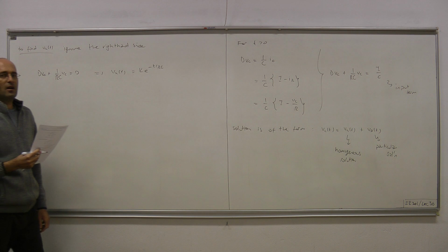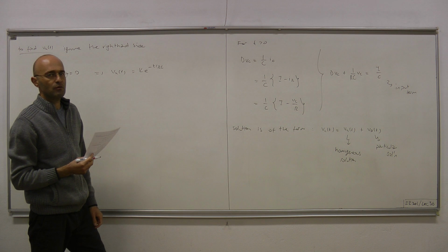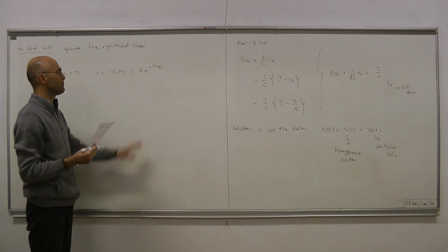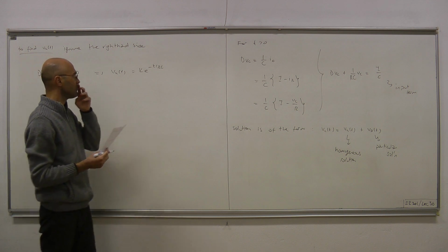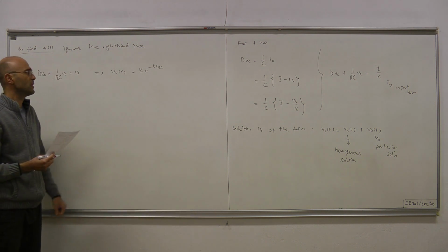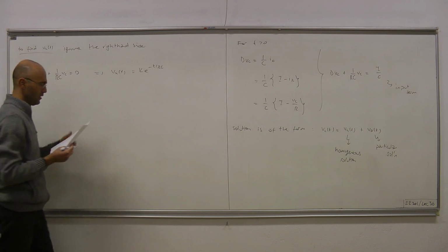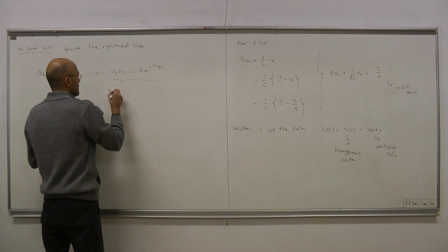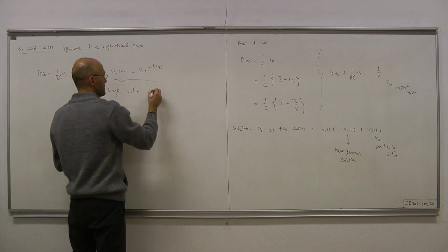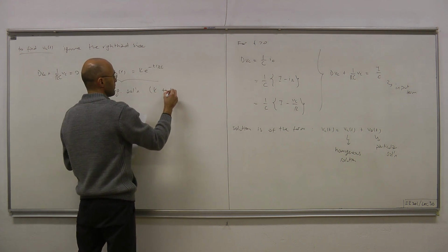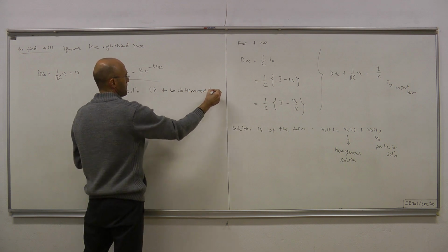For the zero input case, we determined this K using the initial condition voltage. But this time, we just let K be. This one we don't touch now. So that's our homogeneous solution, and for any K, clearly, it satisfies this homogeneous differential equation. This is the homogeneous solution, and K is to be determined later.